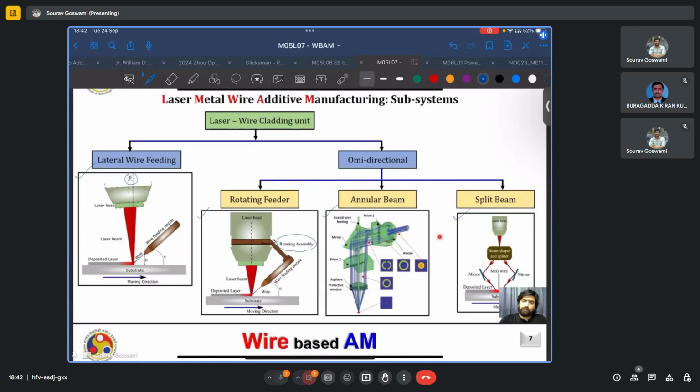Laser optics are very fragile and costly, and so we would like to preserve them and prevent any sort of damage whatsoever. However, tilting by just this small angle ensures that even if there is some reflection, it will occur at an equal angle to the normal, so at an angle beta, and it will avoid the laser optics.